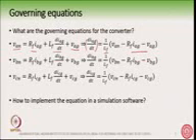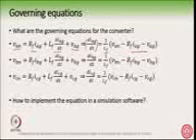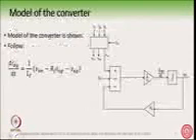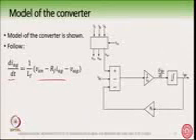However, this equation is also useful when we make a simulation block with this VSC. So let us see how we make the blocks in simulation with this equation. As I told you, we have this equation here. How can we implement it in, for example, MATLAB or any other software? First we get VAN. As I told you, we have just now elaborately discussed how we get VAN from the switches and the VDC voltage. So you have got VAN, VBN and VCN.